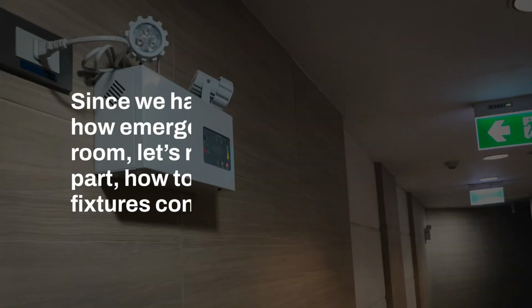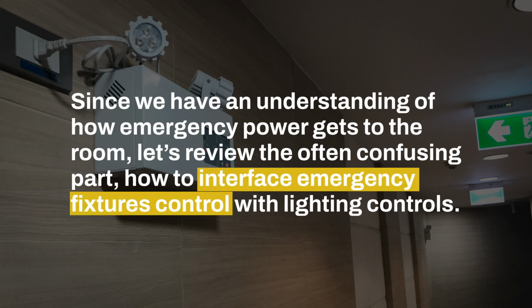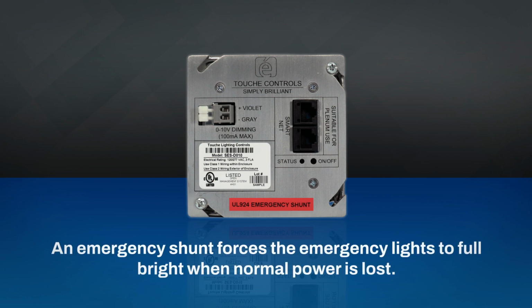Now that we have an understanding of how emergency power gets to the room, let's review the often confusing part, how to interface with lighting controls. There are a few different ways to accomplish this, but commonly an emergency shunt is used. An emergency shunt is a device that when normal power is lost, it'll automatically close the emergency power relay to turn the lights on regardless of what the lighting controls are doing.